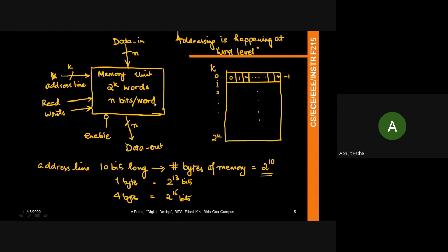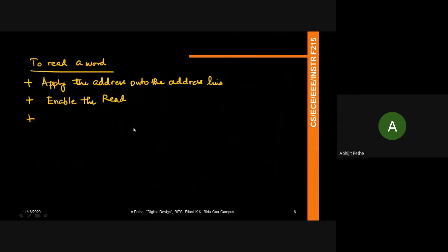So if I want to get the data, once I've enabled the read, I should not immediately go and pull the data from data out. Once I've enabled read, I will ensure that data out has transitioned completely before I start reading from that port, right? So remember, the order, the sequence of events becomes important.